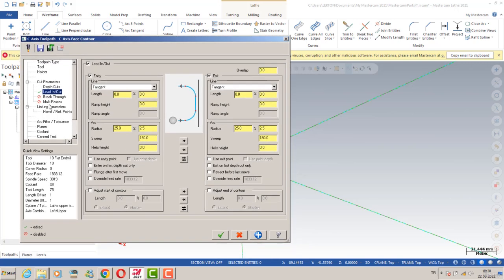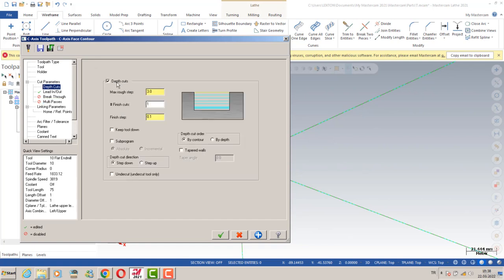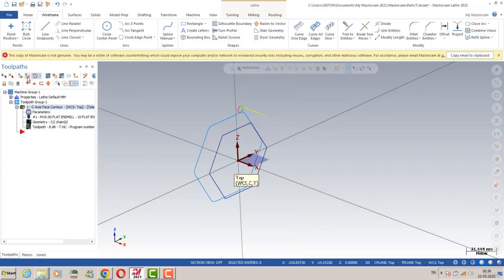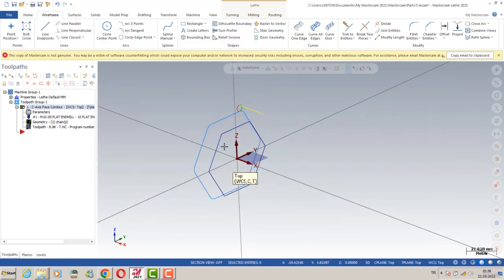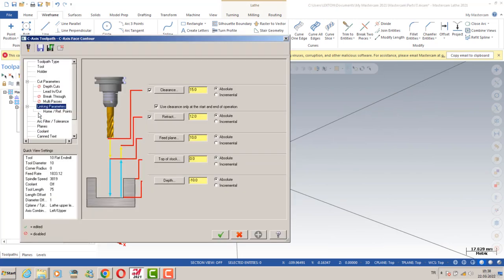And maybe we should also talk about the multi-axis options. For that, I'm gonna unselect our depth cut options. You're gonna see that this is 10 millimeters. I'm gonna click here, and we can recalculate our toolpath. At that point, actually, I'm gonna click here.